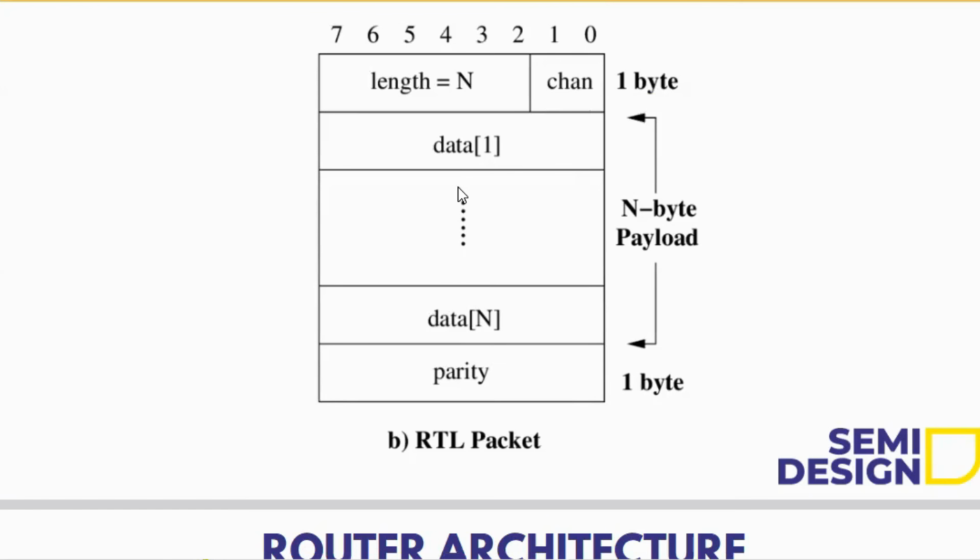When the second data byte is added, that stored value is again XORed. Bitwise XOR is performed with the second data, and it will be again stored in that register. And it will do an XOR of that stored value with the third data, and it will generate another parity. This parity generation will occur parallelly, and this parity generation will occur at the end of this packet.